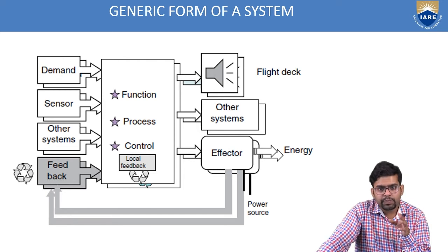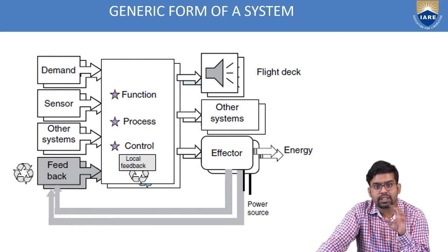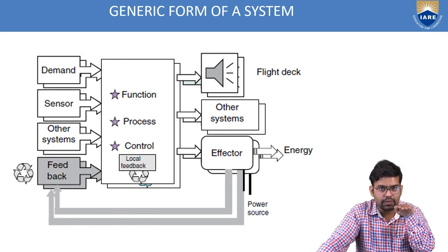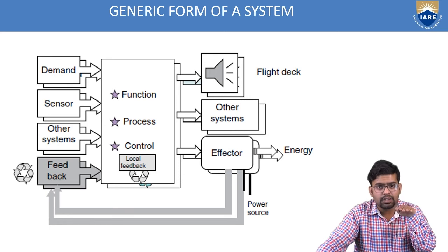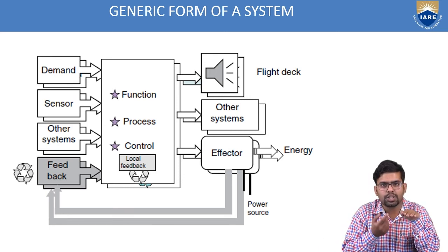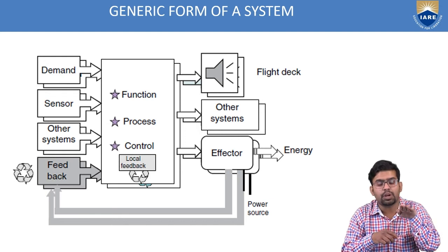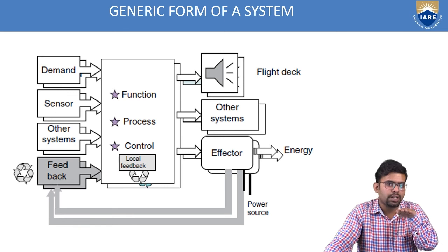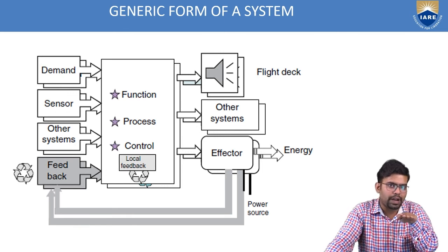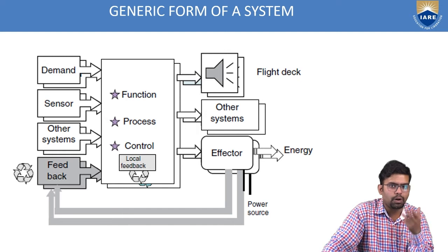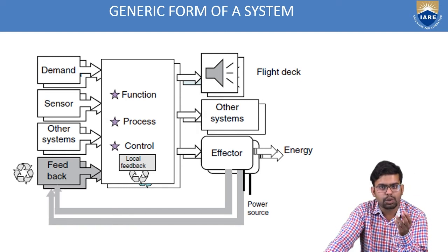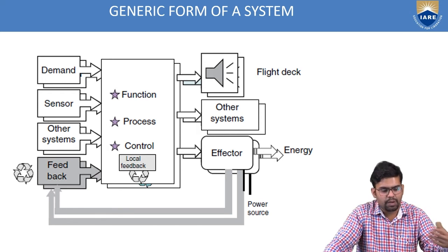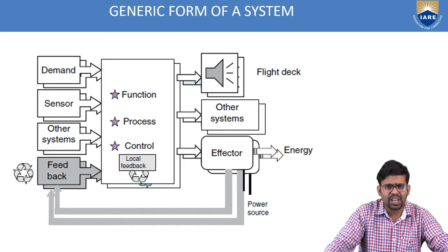The problem is, it actually had some problems with its input. So even though the aircraft was in exact flight level, good flight level, it understood that the aircraft is actually pitching down, and it gave a pitch up moment. So this pitch up moment, when it comes all of a sudden, the pilots actually didn't have a clue of what is going on. They didn't have any clue. So they were actually trying some other issues instead of attacking the MCAS system.